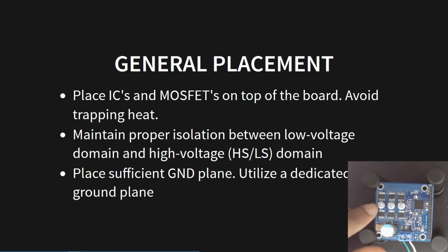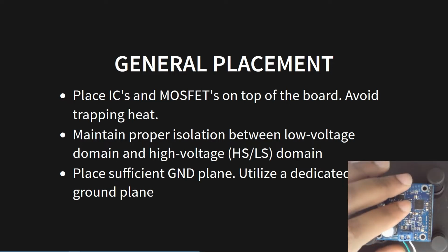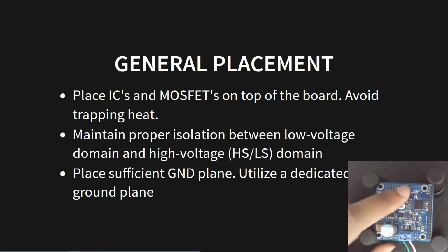Another thing is you want to place sufficient ground planes, and utilize a dedicated ground plane, which I've already done. This is a 4-layer PCB, and they'll be mentioning more about ground planes in here. So I've kind of already followed these placement methods.